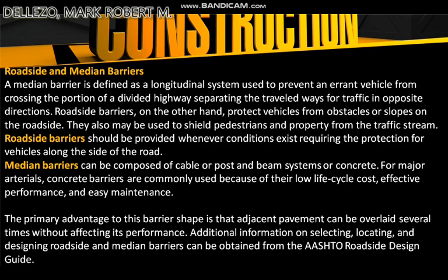Median barriers can be composed of cable, or post and beam systems, or concrete. For major arterials, concrete barriers are commonly used because of their low life cycle cost, effective performance, and easy maintenance. So the primary advantage of this barrier shape is that adjacent pavement can be overlaid several times without affecting its